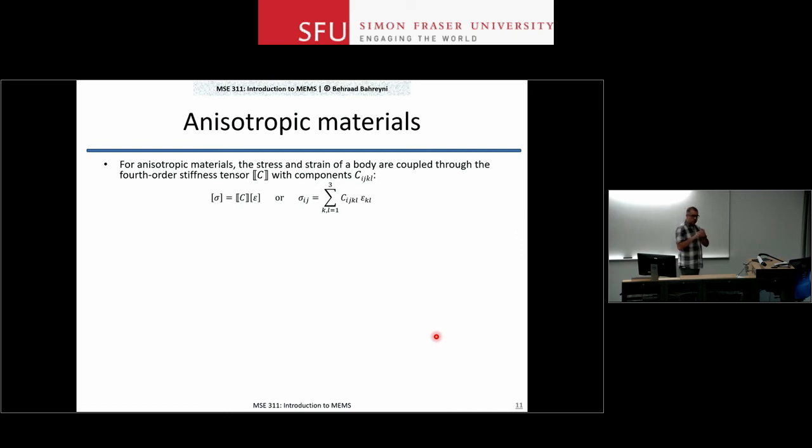Depending on how you pack these atoms in one direction versus another, you expect to see a different stress-strain relationship for different directions. And this is true for anisotropic materials in all cases. Now, in the most general case that you can imagine, each stress component will be proportional to all of your 6 normal and shear strain components.